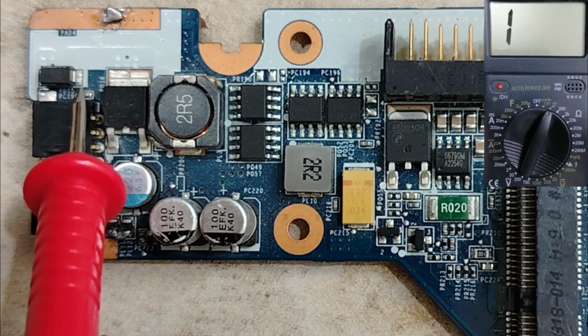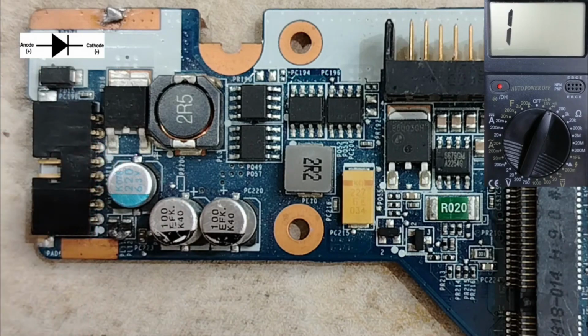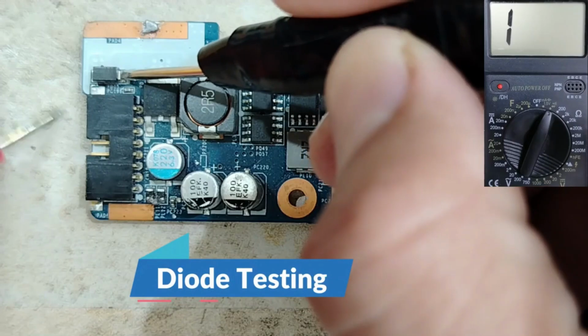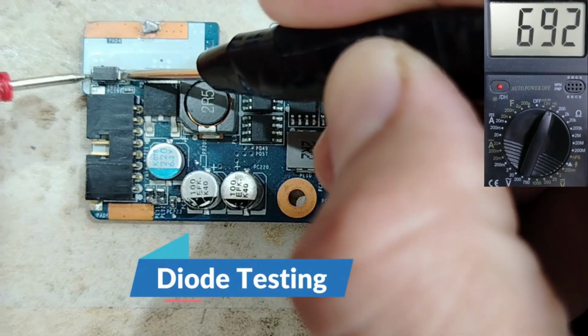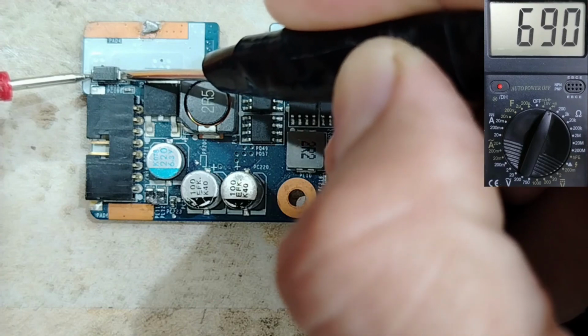We have this white mark over here, which means over here we have the cathode and here we have the anode. So we're going to put one probe here on the cathode and the other probe on the anode. We get a reading in the multimeter. This is a good diode.